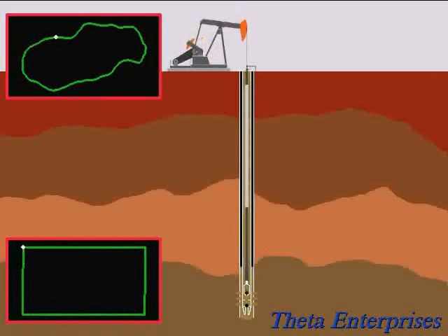Yeah, but what this reminds me of with your question is, I wanted to bring up the fact that when you have over travel, which in the traditional definition means you have a longer stroke at the pump than you have at the surface, that actually makes the plunger move faster, because the plunger has to cover the longer distance in the same time that the polish rod covers the upstroke and downstroke. So if you have 100 inches at the surface and 140 inches at the pump, the plunger has to move 140 inches in the same amount of time that it takes to move 100 inches at the surface. So the plunger is moving a lot faster.